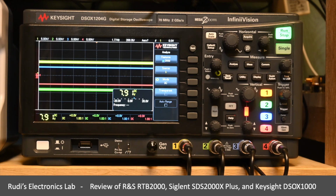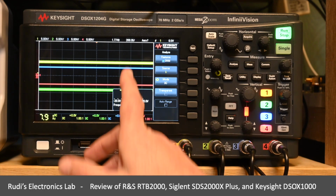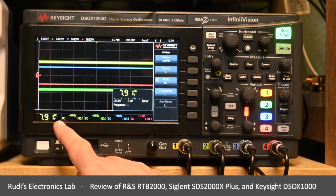And I almost forgot to show you how this particular meter deals with the channel coupling settings. Because as I explained also, this device basically uses the ADC for its measurement. So now I'm showing again the measurement for channel 1, which is the power rail of 8 volts. That all looks fine. And the channel is DC coupled, so that's why we can measure it.